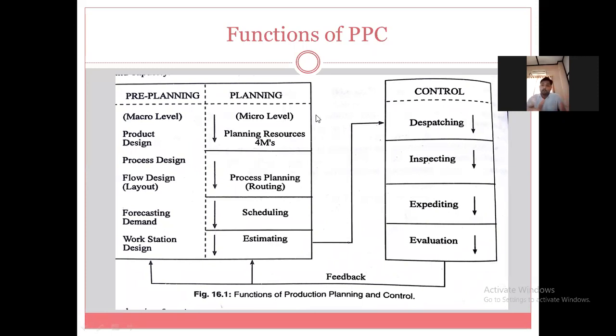Here we have to focus on reducing smaller amounts of time, which will be considered as a wastage of time. If you reduce this searching time, or tool bringing time, or material bringing time, or traveling time, then that time will be utilized for production purposes. In this manner we can increase the productivity of a workstation. So workstation design is useful to increase the productivity of a workstation. All these points are considered at a pre-planning level.